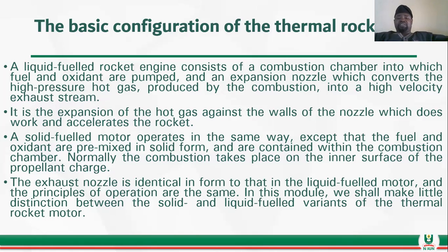A solid fuel motor operates in the same way, except that the fuel and oxidant are pre-mixed in solid form and are contained within the combustion chamber. Normally, the combustion takes place on the inner surface of the propellant charge. The exhaust nozzle is identical in form to that in the liquid fuel motor, and the principles of operation are virtually the same.